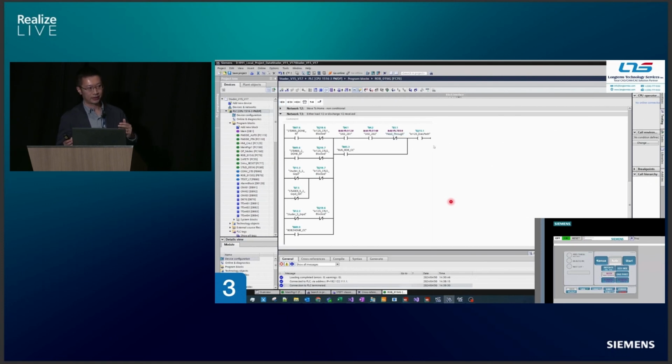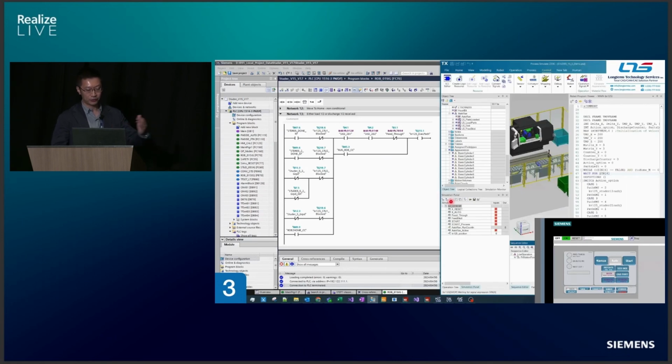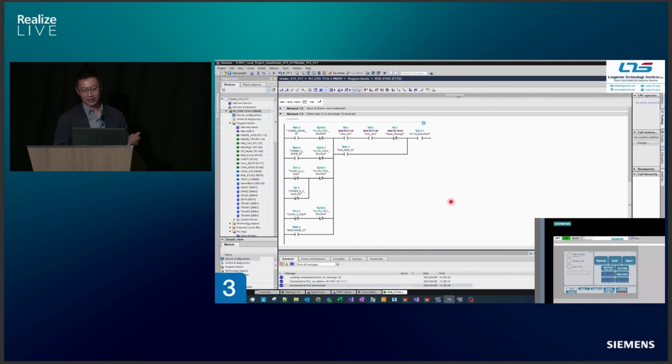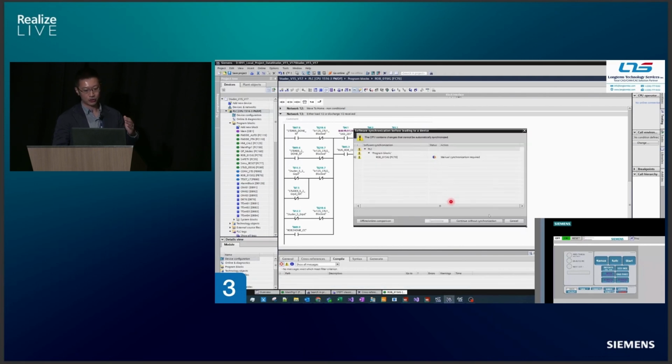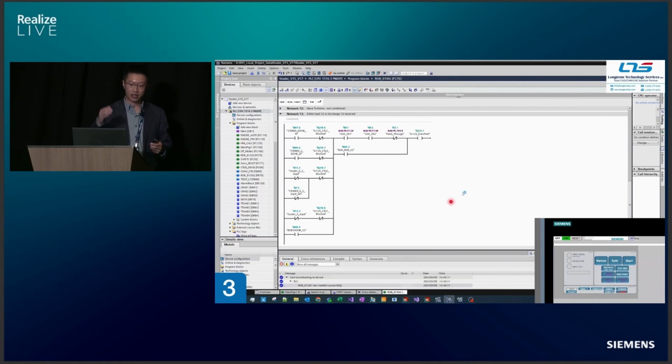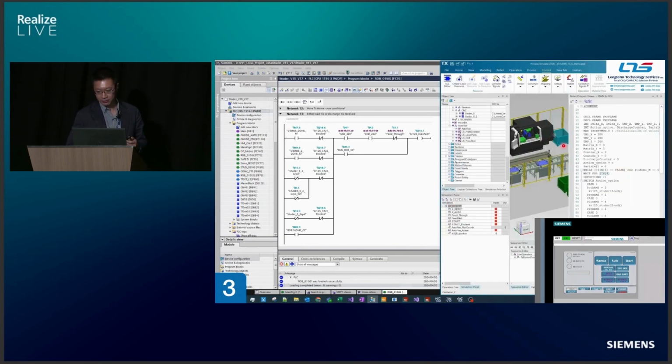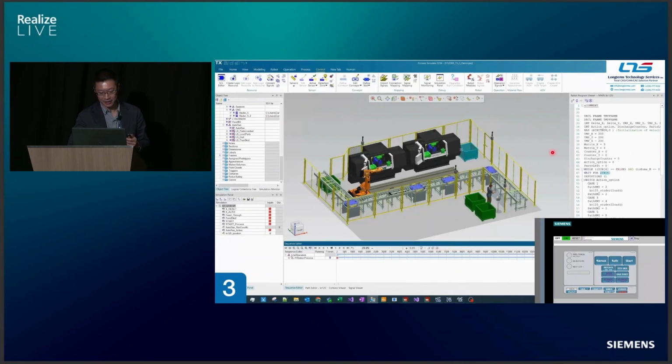right? And again, combined with the previous time scale stuff, you can cycle through all of this code and any change you make, in a faster time scale, so that you can quickly address the issue and validate if your change actually solved the problem. Now we just load it to the PLC, and we're going to see if we actually solved it. Go back to Process Simulate right here. We're going to rerun the simulation, do exactly the same thing, and see if it's actually solved the problem.